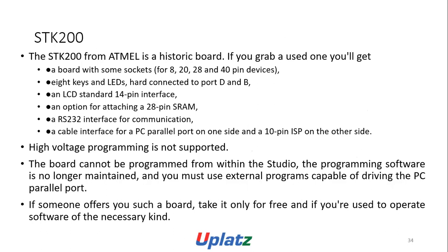The STK200 from ATMEL is a historic board. If you grab a used one, you will get a board with sockets for 8, 20, 28, and 40 pin devices, 8 keys and LEDs, hard-connected to ports D and B, an LCD standard 14-pin interface, and an option for attaching a 28-pin SRAM.